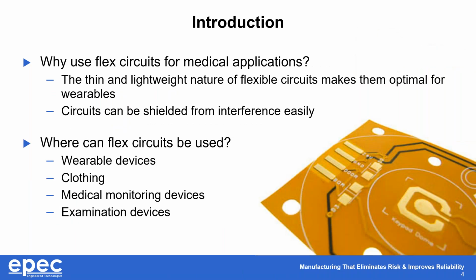So the first question is always, why use a flex circuit for a medical application? Why consider a flex circuit versus just straight wiring or any other alternative? The go-to answer ends up being that flex circuits are just thin and lightweight in nature from the get-go, and that makes them optimal for many applications such as wearables, and they can be shielded just as easily by just a few alterations to the stack up.